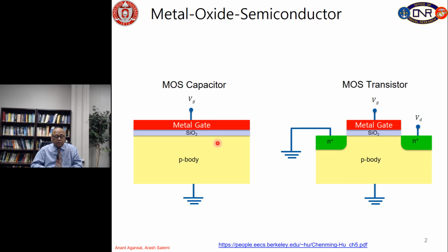This is normally thermally grown on the silicon or silicon carbide semiconductor. And then in old days we used to have a metal gate such as platinum or some other metal. So that's why the name stuck. It's called Metal-Oxide-Semiconductor. These days this metal has been replaced with polysilicon gates, which are doped N-type with phosphorus.